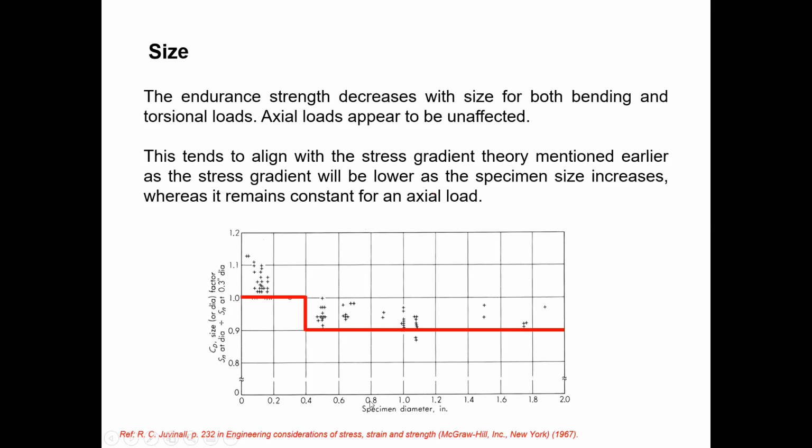It is inches, and you can convert this inch value to millimeters. You can see 0.4 inch. Until that point the size factor equals 1. If the dimension is more than 0.4 inch, the size factor will reduce to 0.9,